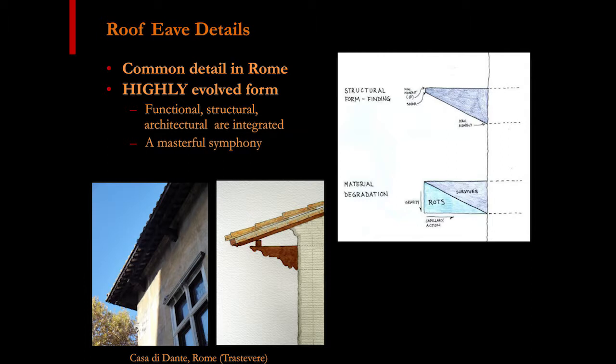And the reason you cut it off is actually preventative, because when you have a straight member that's out in the rain, you've got all this end grain to absorb water. And then think again about our gradient of water. Gravity's taking that water down, while the end grain, wicking, capillary action, and absorption are taking it in. So when you end cut these and expose the end grain to the weather, this tends to be the pattern of rot. And as the owner of a 1914 bungalow that had straight cut joists like that, I can personally testify that that's exactly how they rot. So you want to cut that off, cut off the cancer before it infects the whole structural member.